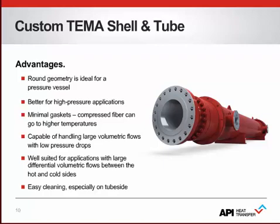Flexibility and design features such as shell sizes, tube counts, and pitch make the shell and tube well suited for large volumetric flows, especially when there's a wide differential of flows between the shell side and tube side. The tube side of a shell and tube is also easily cleaned by chemical flushing or mechanical brushing of the tubes. The head channels or covers simply need to be unbolted, providing access to the tube sheet and the tube internals. This is a simple maintenance procedure in most any service.